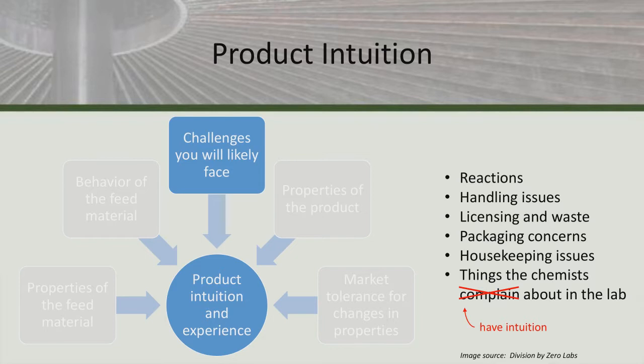Are there packaging concerns? The cost will be greatly affected by this. If you're just going to package in a super sack, for example, that will be much cheaper than if you need to put your powders in a stick pack, and then the stick packs go in a box, and the box goes in a case, and then the cases get stacked on a pallet, wrapped, labeled, and shipped, right? That's going to cost a lot more, and you've got to make sure that the facility is equipped with the packaging line to do that.